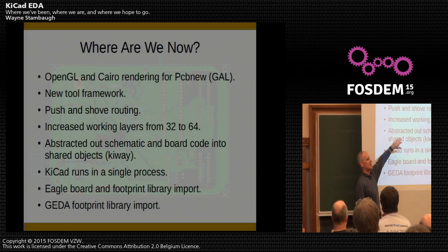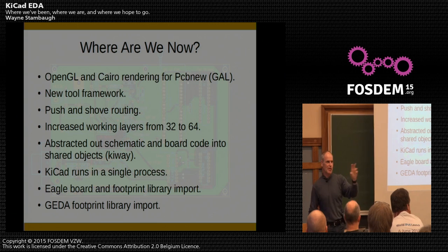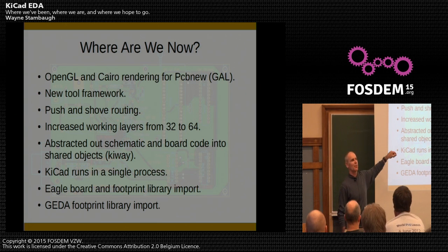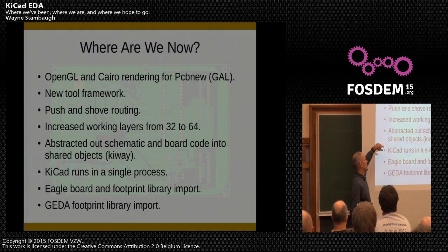The nice thing is that now all of the applications in KiCad, the board editor and the schematic editor, can either run in a single process, as Peter talked about earlier about not defining a workflow. If you're comfortable running them all in a single process, they can all be run as part of the project manager. Or you can launch the schematic editor standalone and edit away on your schematic that way, if that's your preference. They're both in there.